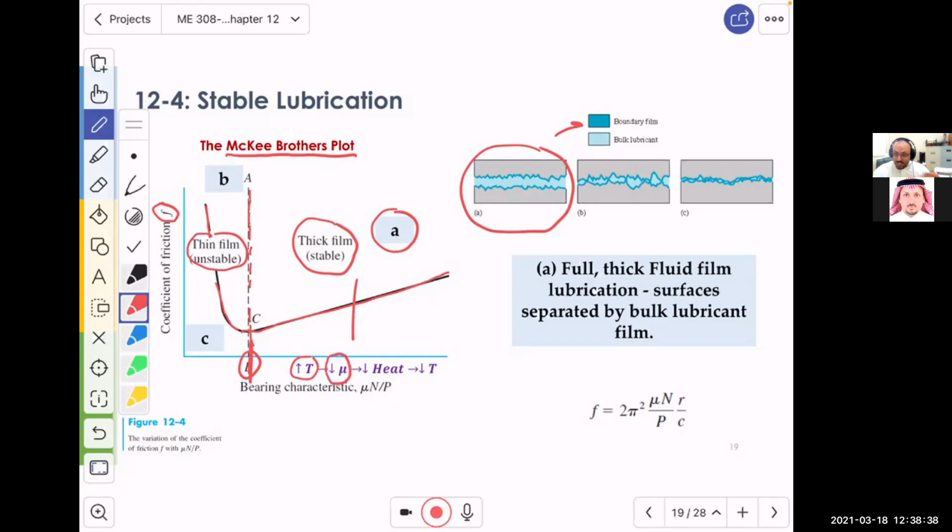Next, the viscosity drops. We all know that the more viscous the fluid, the more friction it generates. So if you drop the viscosity, the heat generated by the fluid, the lubricant, will drop. In other words, the temperature will not increase. It may even drop, which means that you increase the temperature and the process itself ends up dropping it or stabilizing it. And that's what you want.